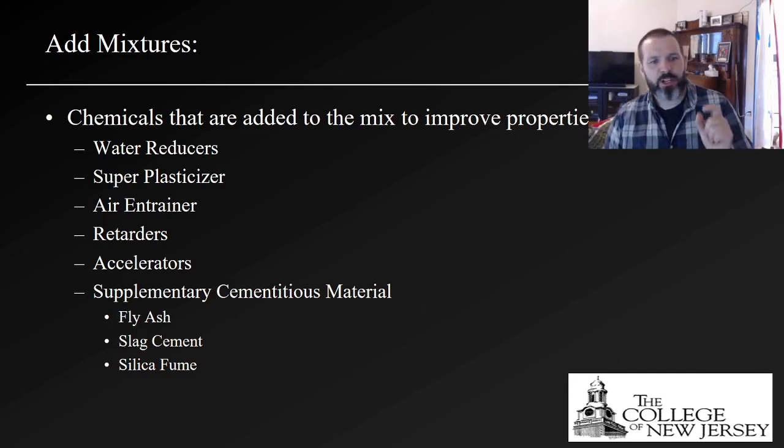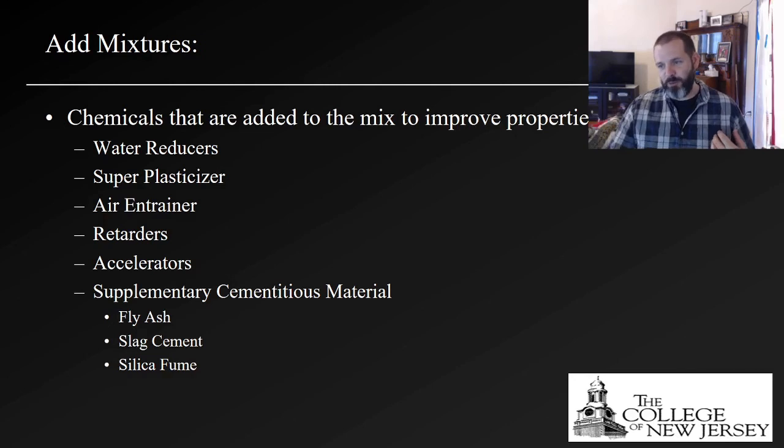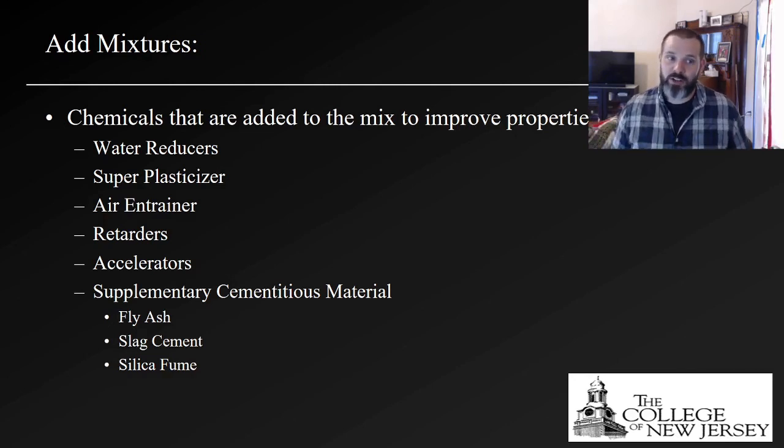And what they allow for is when water gets in your concrete and it freezes. Water is a very interesting substance in that when it goes from its liquid to its solid phase, it actually expands. So when water gets into your concrete and freezes and expands, instead of cracking your concrete, it will fill into these air bubbles. And when it freezes, it stops it from damaging your concrete. So air entraining your concrete, while reducing the strength a little bit, adds durability to it.